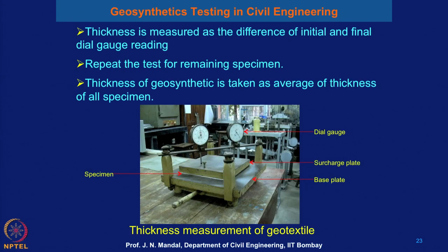Here is the equipment where you measure the thickness of the geotextile material, and thickness is measured as the difference of the initial and final dial gauge readings.